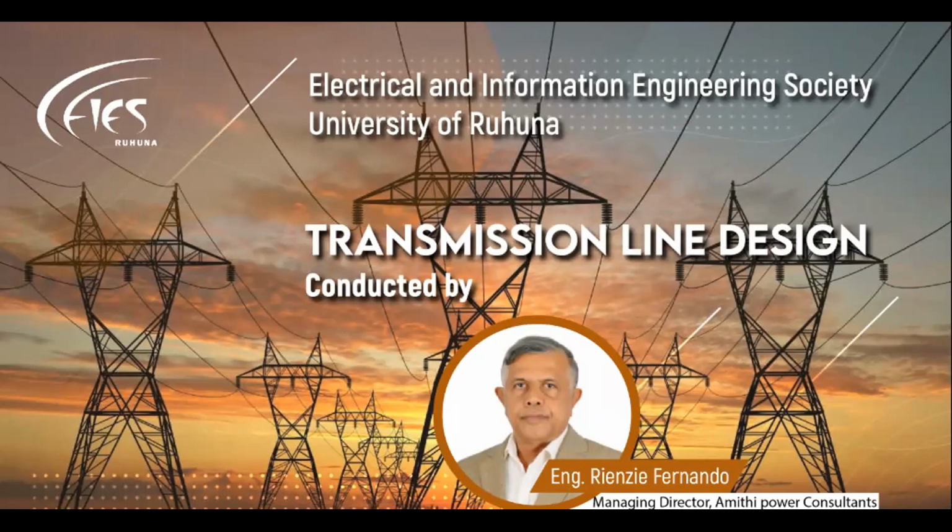So the solution is to keep 25 millimeter per kV, and if you have repeated problems with sea breeze and whatever, go for Dow Corning application. Apply Dow Corning paint and forget it. So it won't flash over. Clear? Please, sir. Thank you, sir.